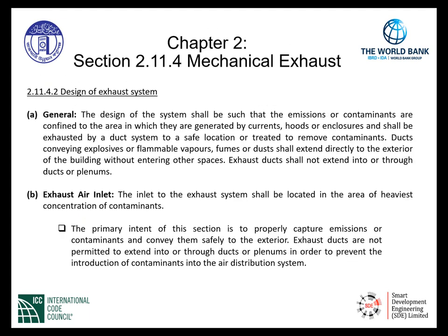Section 2.11.4.2, Design of Exhaust System. Item A gives us a general requirement. The design of the system shall be such that the emissions or contaminants are confined to the area in which they are generated by currents, hoods, or enclosures and shall be exhausted by a duct to a safe location or treated to remove contaminants.